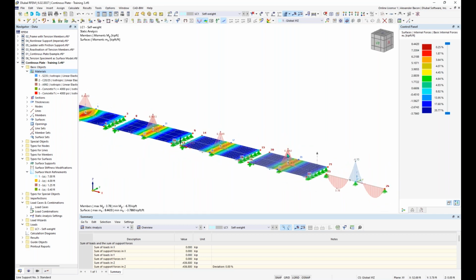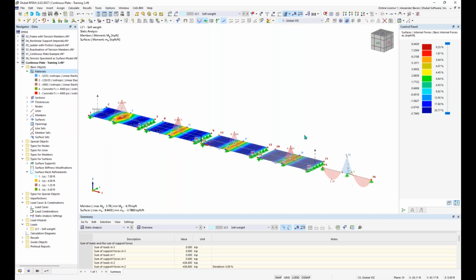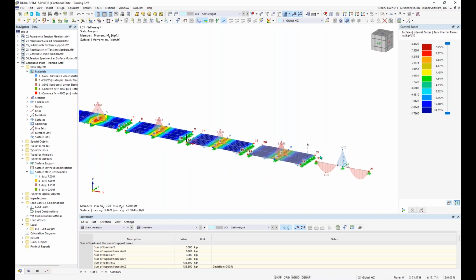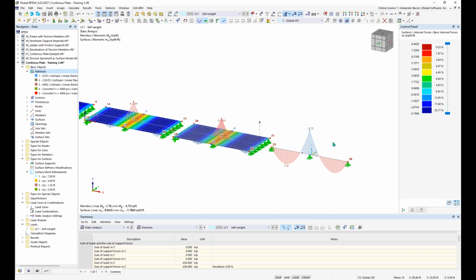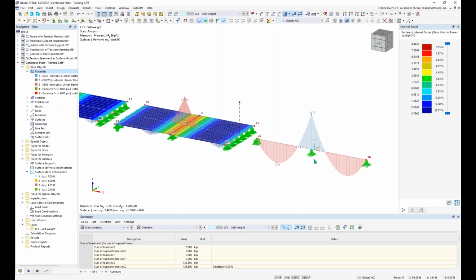And yeah, so in RFEM, we can now talk about shear stiffness. With shear stiffness, when it comes to hand calculations, if you're trying to, for example, do hand calculations to match the results of the beam here, you have to take into account shear stiffness effects. Taking into account shear stiffness is what RFEM does in the program. And what this does is it leads to increased deformations due to shear forces. This is something that is not taken into consideration with hand calculations. With hand calculations, you assume that a beam like this has infinite shear stiffness. And so this plays a major role when it comes to a material like concrete as well.